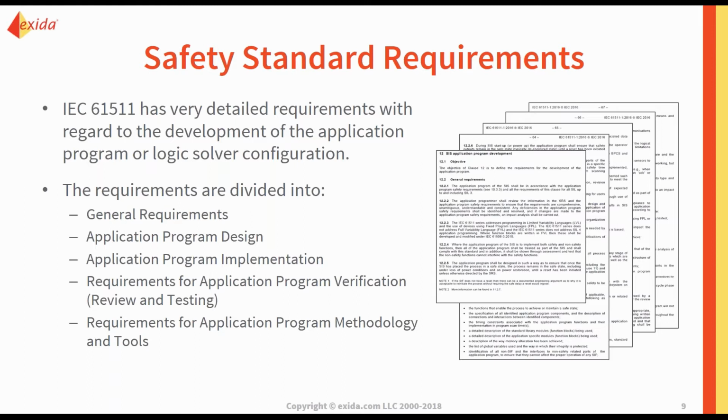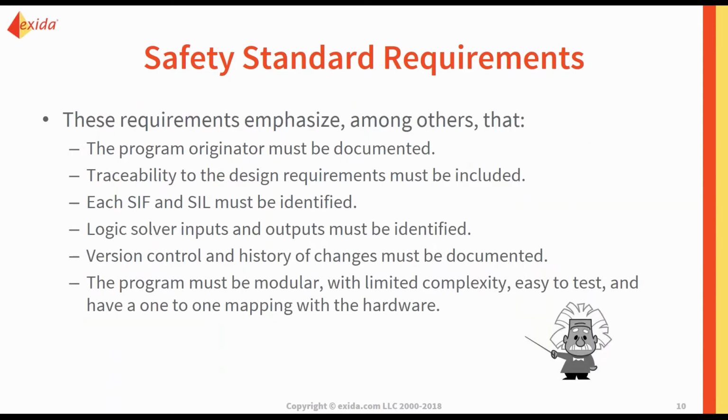These requirements are divided into general requirements, application program design and implementation, requirements for review and testing, and then the application program methodology and tools. So it's pretty extensive in the standard. I have attempted to summarize it here, but basically the crux of it is that your configuration of the safety logic has to be consistent with your design.